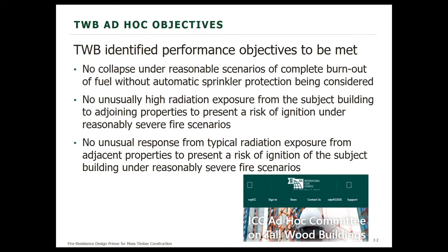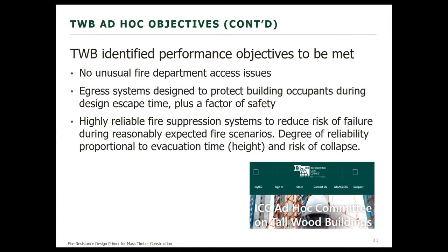These are the ad hoc objectives, and what they wanted in the end: they wanted to make sure that there was no collapse under reasonable scenarios of a complete burnout of fuel without sprinkler protection being considered, no unusually high radiation exposure from the subject building to adjoining properties, no unusual response from typical radiation exposure from adjacent properties to the taller wood buildings.